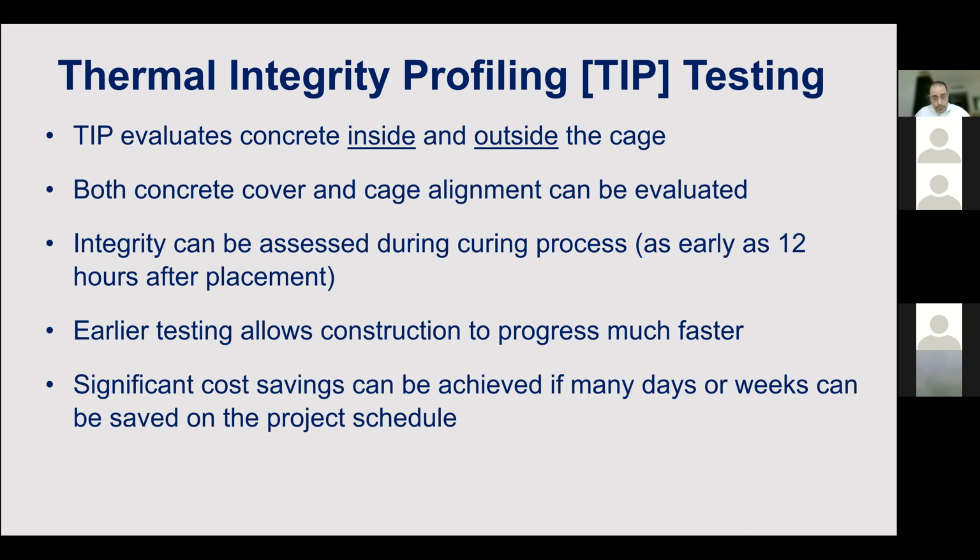Assessment of the integrity can be done during the curing process, which happens relatively fast, and within 12 hours from placement, you can already see the results of the integrity. If you are able to see the results within a relatively short period of time, this gives advantages in terms of allowing the contractor to get approval and allowing the construction to progress faster if the client requires regular approvals to continue.